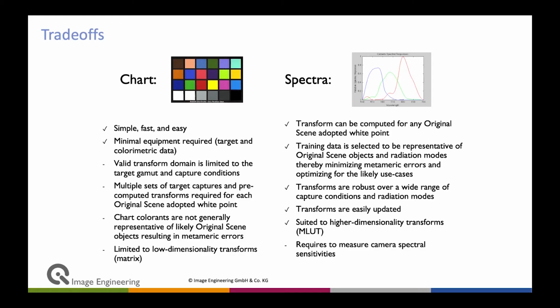The big benefit is if you want to, and in many cases you really want to, optimize your color correction matrix for different illuminants. So you want to have a different 3x3 matrix or conversion for a warm indoor light compared to daylight outdoors, or to your own light source that you bring with the camera.